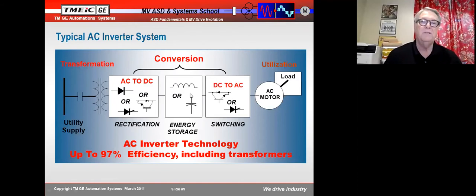Then we have some kind of energy storage mechanism. So basically, the motor runs off the DC bus. It doesn't run off the input, it runs off the DC bus, so we have to have some energy storage there. And then this converter basically just keeps the DC bus charged. We can store that energy in two ways, either in an inductor or in a capacitor.